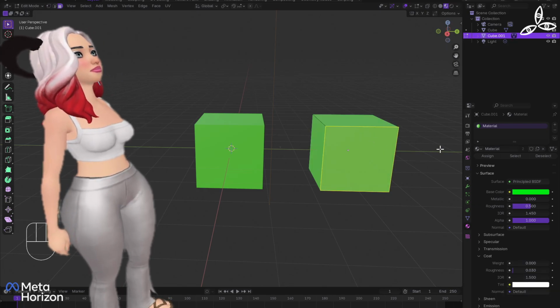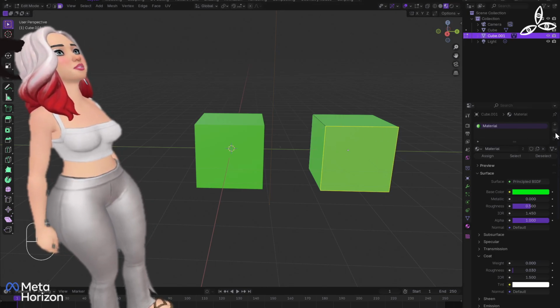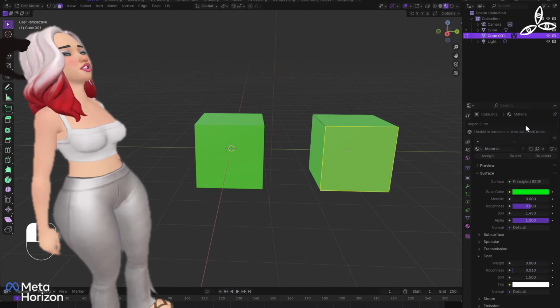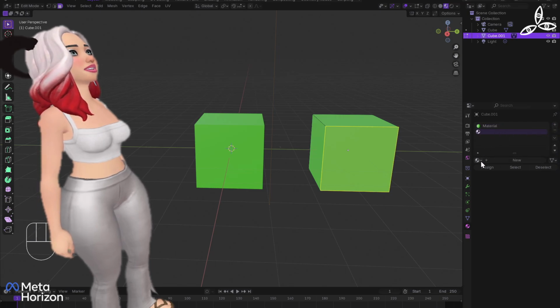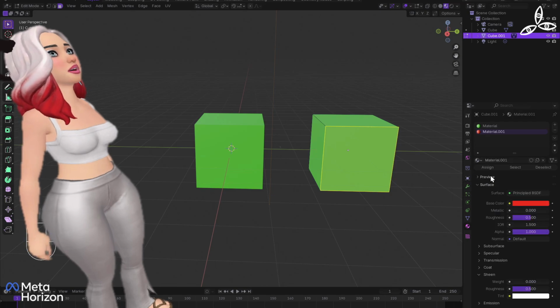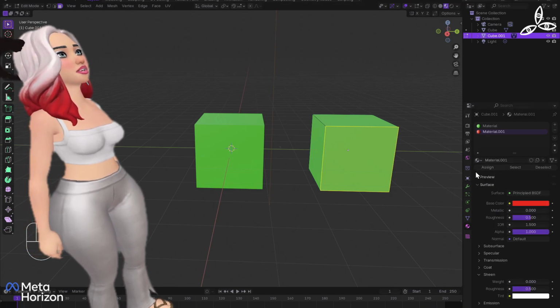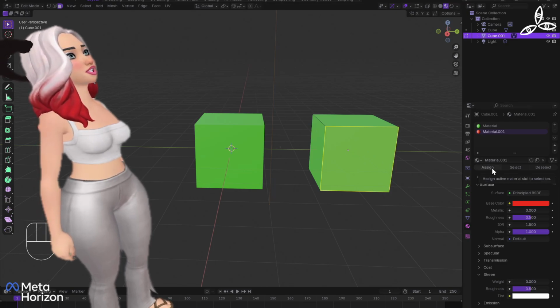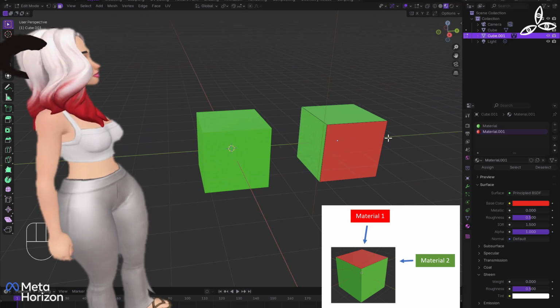So if I click on this face here, and I add a new material slot, because I don't want to disrupt the existing material slot on the object. Let's see, I actually can't remove the material slot in edit mode, it doesn't want me to do that, that's fine. I click add material slot, so I add a new one, and then I can select material 001, great, and I can actually apply that. So I click the assign button with this face selected.